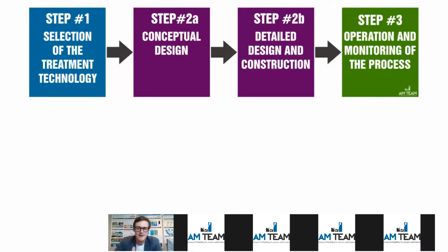So we typically feed the model with data that is very readily available at plants. A very important one is flow rates. Another one is some samples on DOC, or some people have online DOC, or some samples on UV254 absorbance, or some people have some spectral online data.